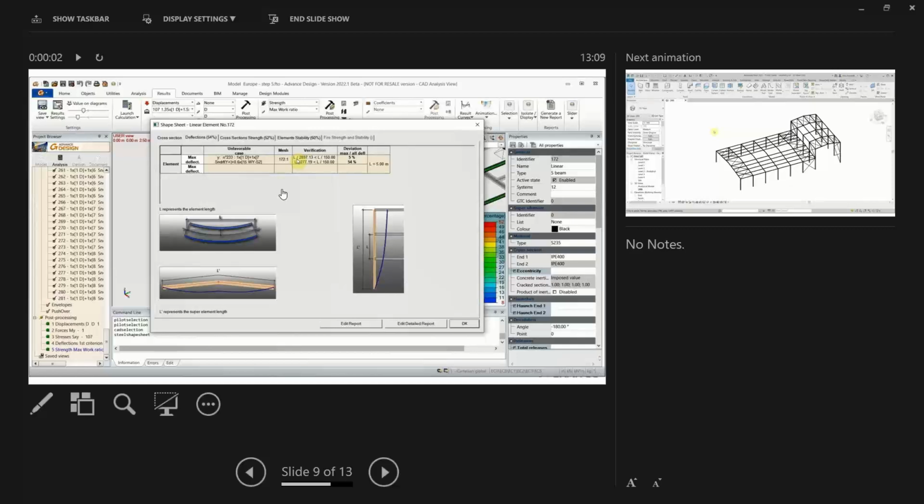Here we can see that 54% deflection is coming from, there's the reference to the mesh and the unfavorable case. So case number 233 is resulting in worst case deflection. So it will always show you the worst case deflection, which case is resulting in that, which mesh, which node is where it's highest.